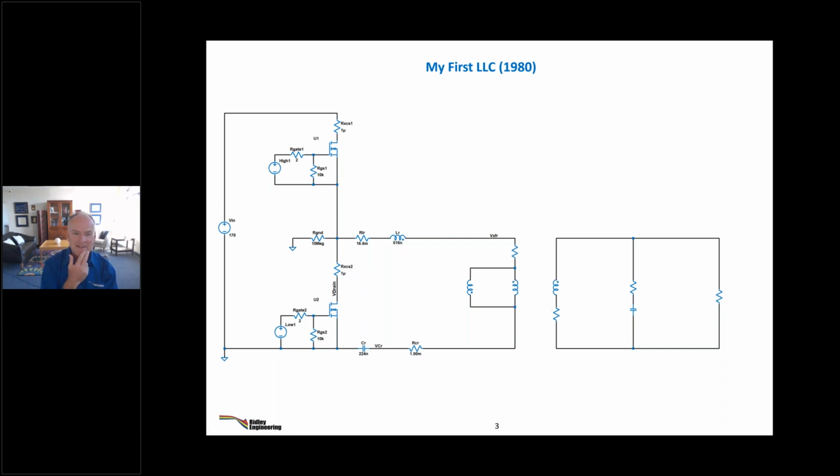Now, why is this important? It's not what you're going to build if you're an LC. Well, when I was winding these transformers, they would fail on a daily basis because I didn't know how to get around the 6,000 volt corona issue until much later into the project. But something that never really failed very often was the bipolars on the primary.